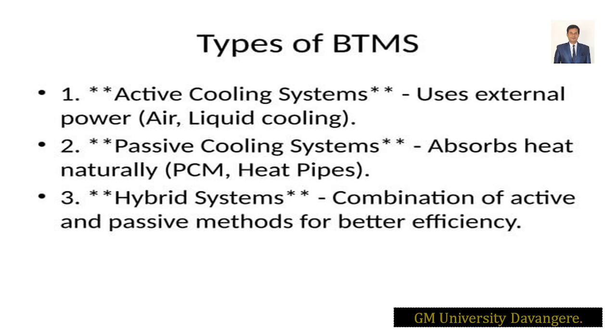So there is no energy used from this PCM material. There is zero power drawn. When you think about the active cooling, there is a certain power usage, around 1 to 3 kilowatts of power drawn by the fan to cool the cells of the batteries. All right. The hybrid system is nothing but the combination of both active and passive cooling. Passive cooling is for normal time, plus the active kicks in for fast charge or hot days, right?